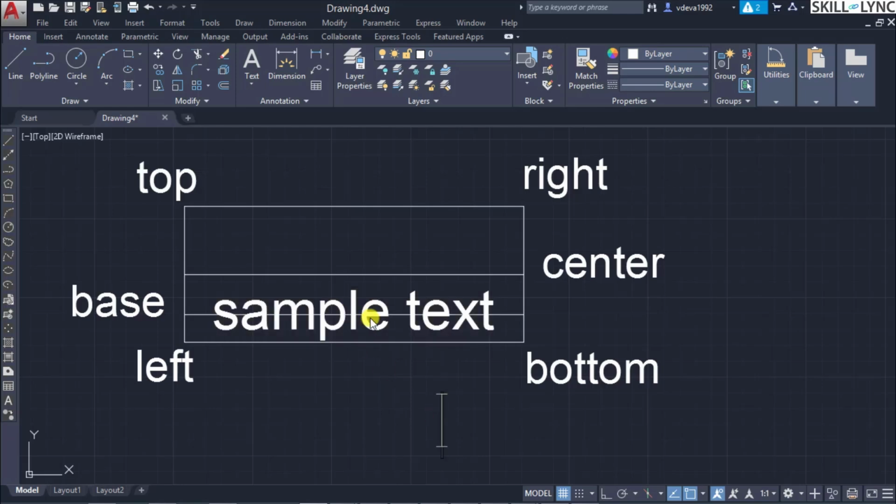As you can see, it is holding within the middle point of this text object, as well as the center point that we select is the center of the axis as well as the center of the baseline. Whereas earlier when we selected the center option, it aligned on the baseline but with respect to the vertical center, but here it goes to the center of the baseline itself. So this is your middle command.